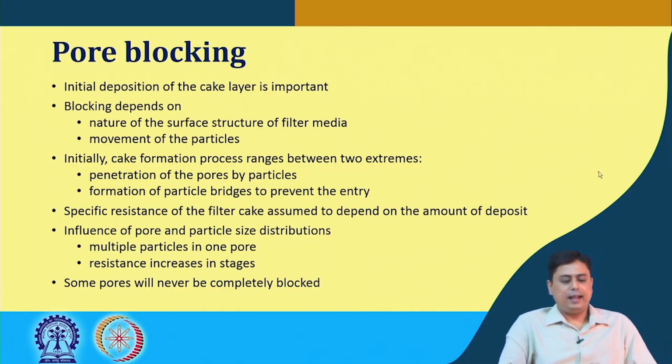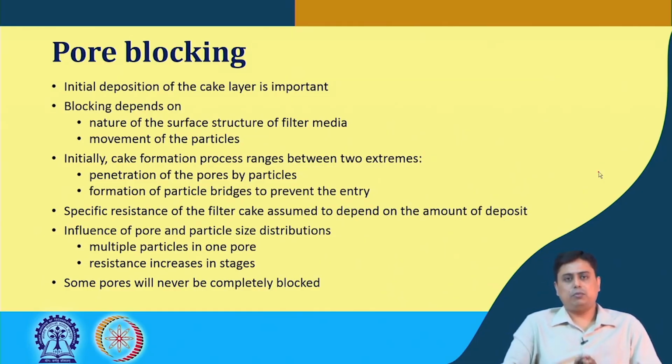So, the point is that this initial cake formation process ranges between two extremes. One is the penetration of the pores by the particle, the other is the formation of bridges to prevent this entry into the pore. So, this process basically plays in this two extreme range, sometimes one, sometimes the other, and most of the time it is the interplay between these two.